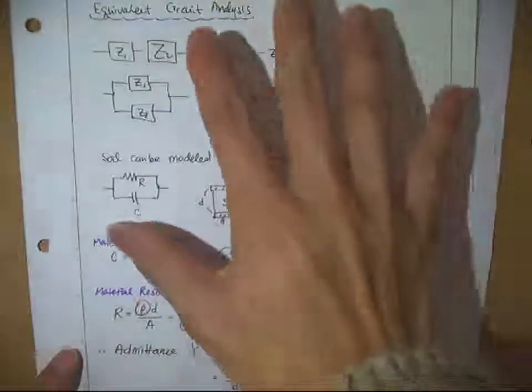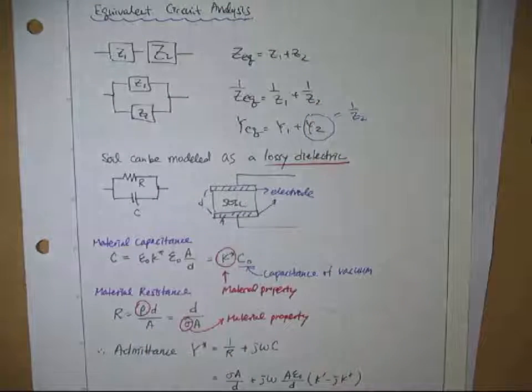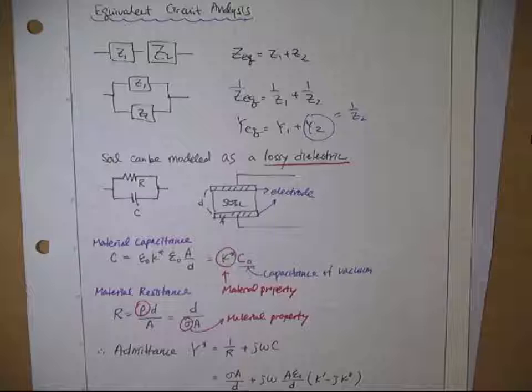Okay. I'll just briefly show you, and then we're going to do this one again on Thursday. Let's imagine that you have two electrodes, parallel plates, and you're putting the soil inside. So maybe like a consolidometer. You're doing the consolidation, and you're measuring the electrical property of the soil. For that, your bottom plate is metal, and the top plate is another metal, right? Then you can measure the resistance and so on.